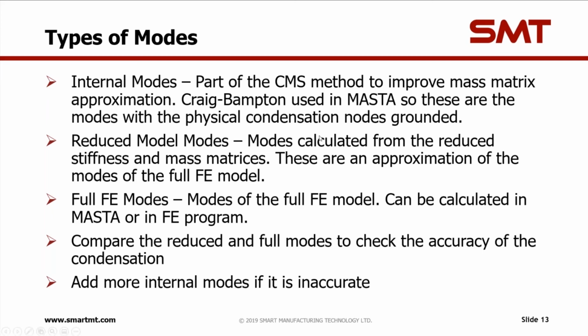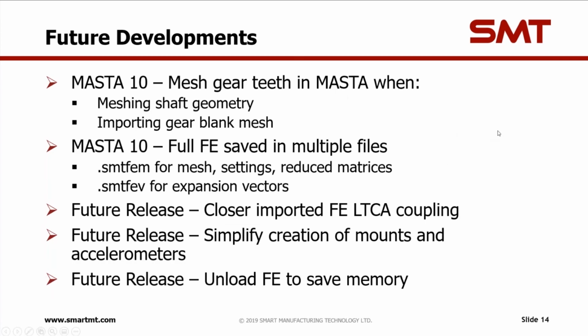So if I just run through quickly what we're working on in the future for FE as well. There's a couple of new features in MASTA 10 coming up. The first of these is the option to mesh gear teeth in MASTA. This is available when you're using the shaft geometry meshing within MASTA, or also when you're importing a gear blank. So you can import a mesh of your gear blank into MASTA and have MASTA generate a mesh of the teeth and attach those two together.